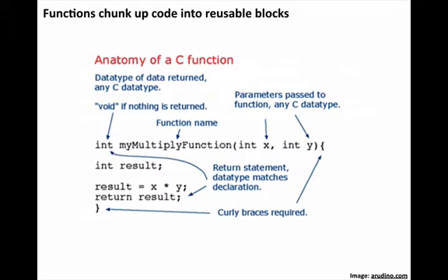So now we're going to get a little bit into the code side of things. When you're writing code in the Arduino IDE, you're really writing pretty much C++. It's very important when you're writing code to break it up into functions, not just have this one monolithic loop block. You want to break things out so you can reuse them, and so they're easier to maintain and easier to see the flow of the program.